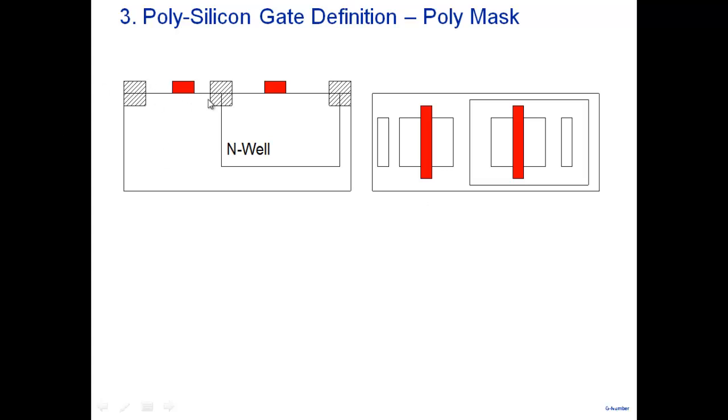So typically what would happen is that, note that this is silicon dioxide, but this silicon dioxide and all that is for isolation purpose. It's not for making a transistor. It's pretty thick and it's not of that high quality. While here, what would happen is a very thin layer of very high quality silicon dioxide would be deposited, because that will act as a gate insulator. On top of that, polysilicon will be deposited, and then you will etch away polysilicon and gate oxide from everywhere else, and you'll leave it here. So I've not shown here the silicon dioxide, but underneath polysilicon, note that there's a thin gate oxide. That's how you create a MOSFET. So there is polysilicon and there is a thin gate oxide, and then there is this one here.